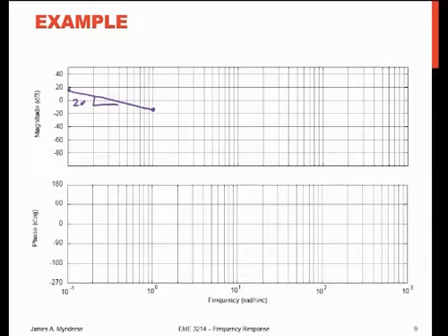That's going to keep going until the next frequency that I hit, which is my zero, which had a natural frequency of 5, so that's right here. At that point, I'm going to make a turn, so I'm going to continue this down.